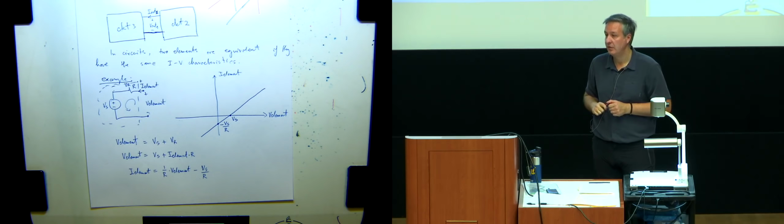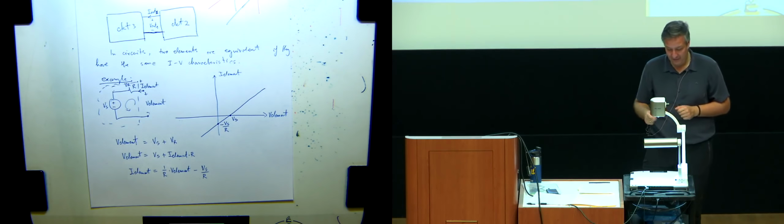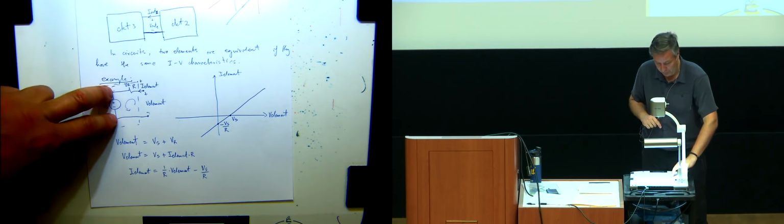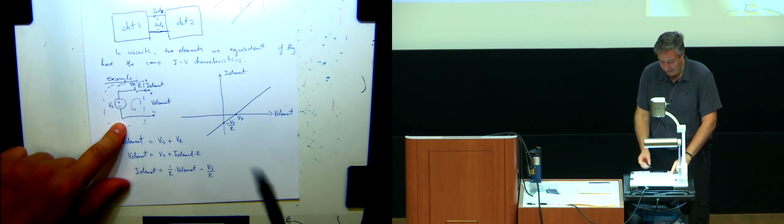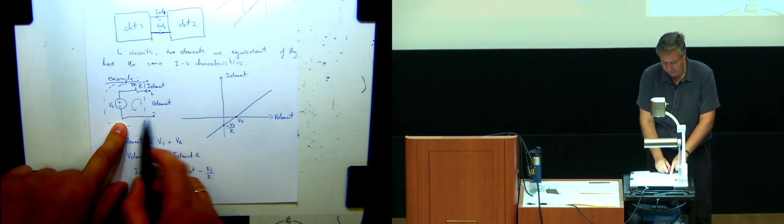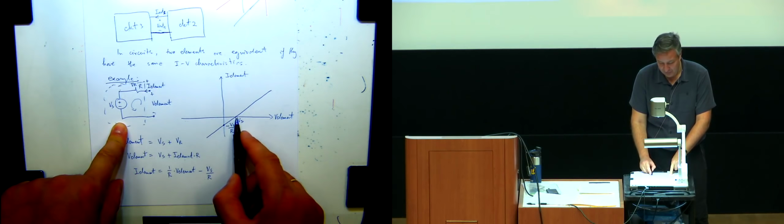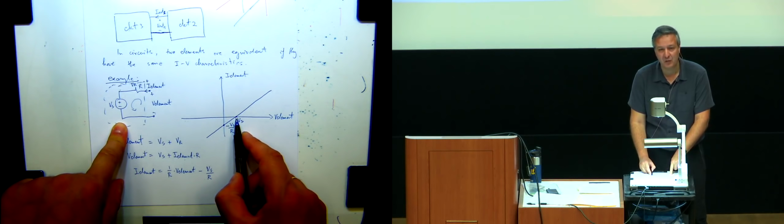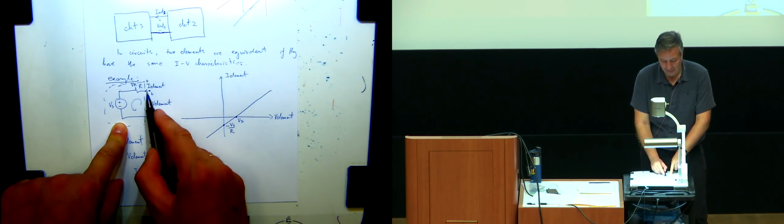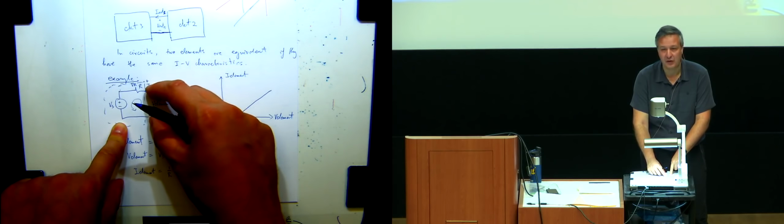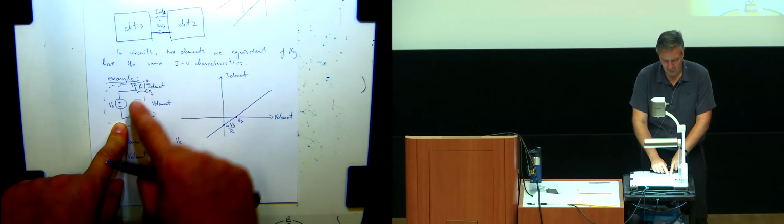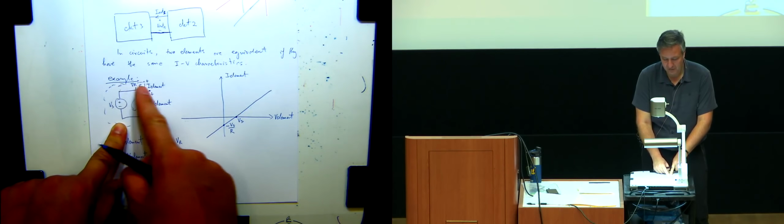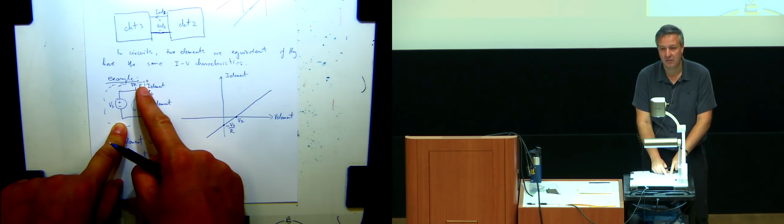Yes? Could have seen that there was a voltage source and start at that value Vs and then draw the slope of the curve. Okay, yeah, I could have done that, like just seen the voltage source and drawn the slope. I need to kind of, this first sentence that you said, when I element, notice that this point here is when I element equals 0, right? When I element equals 0, I know there's an open circuit here. Right? So if I element equals 0, there is no voltage across R, right?